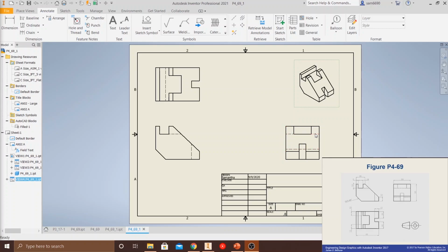These are now the hidden lines, whereas these full lines are what you can see. You would be able to see this, but you can't see this line back here for this chamfer. So that's just some information for you. That means we're going to dimension things a little differently than how it looks here, but for the most part, it should stay the same.